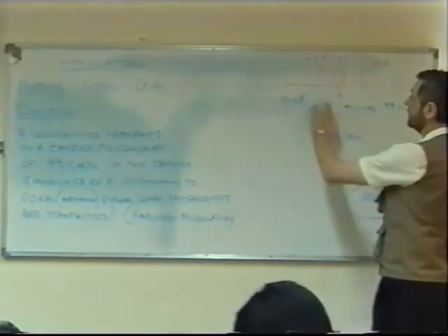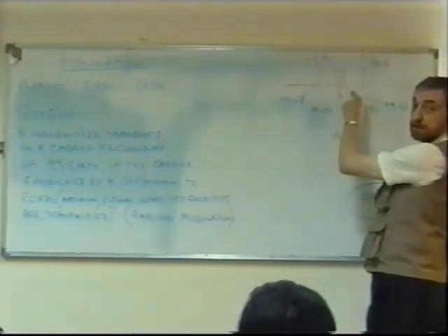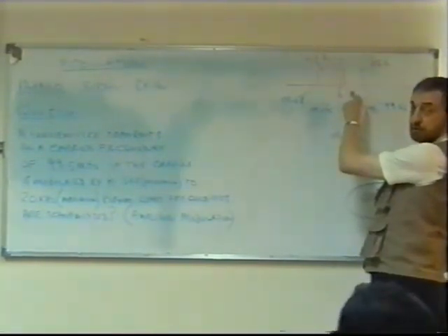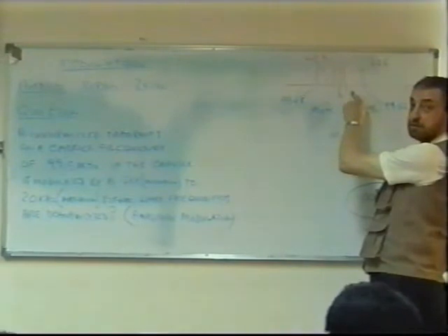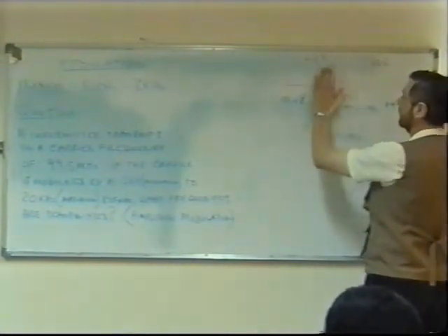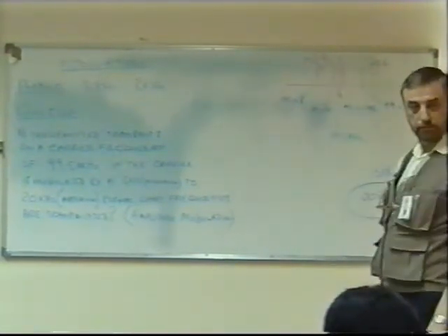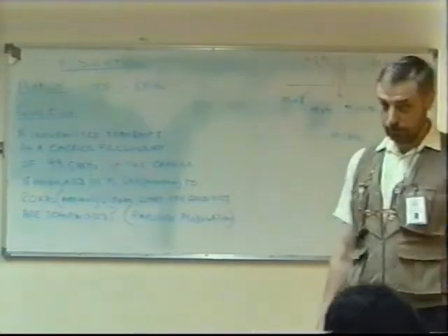There'll also be frequencies between here, perhaps, and here, depending on what's going on. But we're just talking about the highest and lowest, the minimum and maximum. This is our upper side band of frequencies. That's our lower side band of frequencies. That's our carrier. Okay?